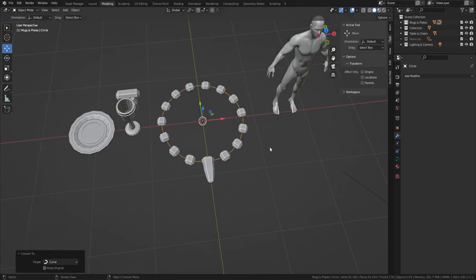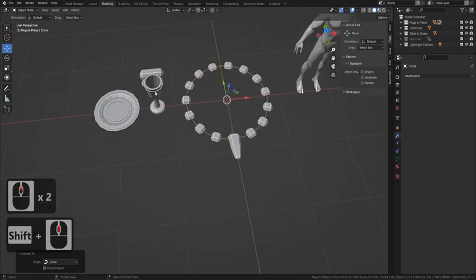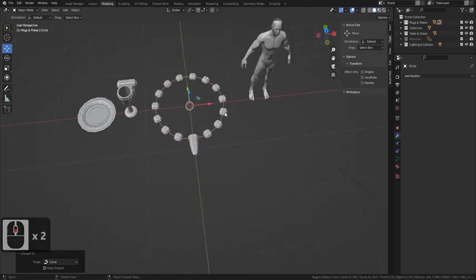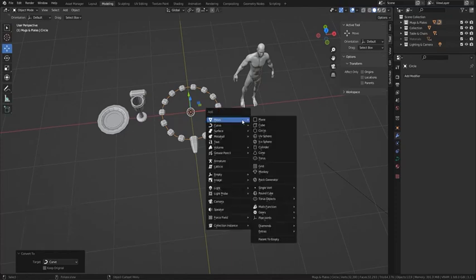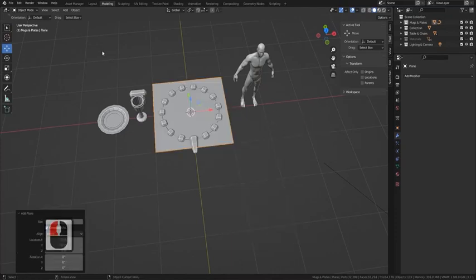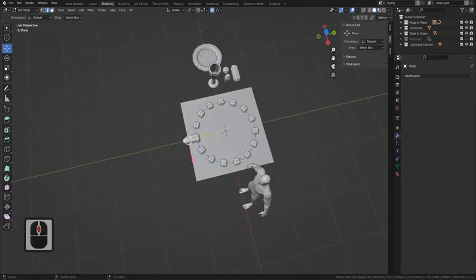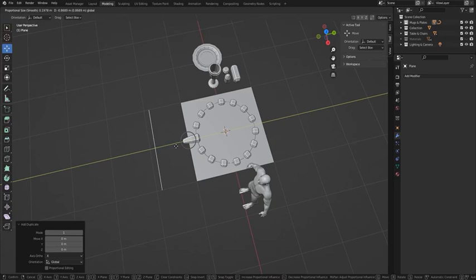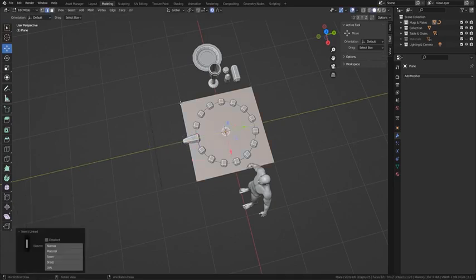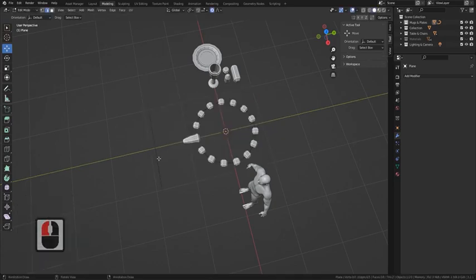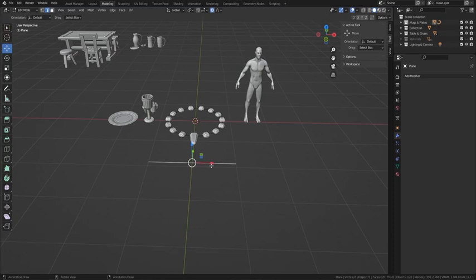Now the best thing with that, just so you know, is you can actually convert any piece of mesh into a curve. So in other words, if I bring in a plane and I press Tab, I'll just do a quick show here. Don't do what I'm doing, just follow along. Shift D, pull it out, and then get rid of the rest of the plane. You can see that I've got this piece here. Then I'm just going to give it a few subdivisions. So right click, subdivide. We've got 4 in there now, as you can see.